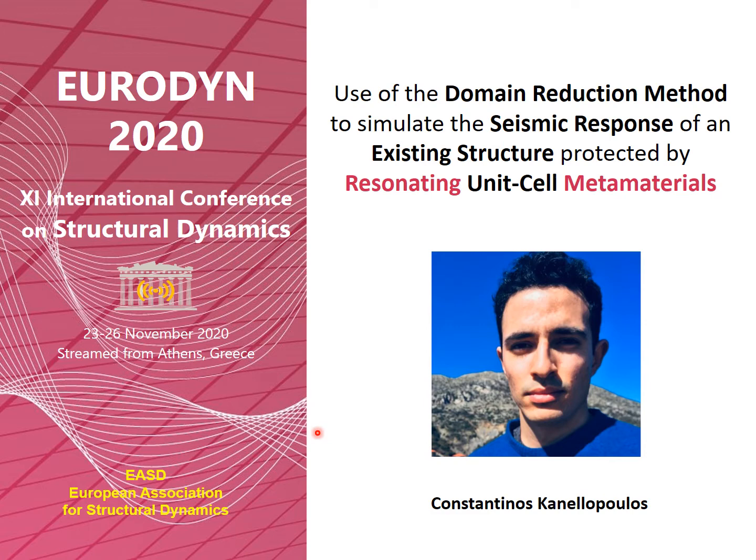My name is Constantinos and I'm a PhD student at ETH Zurich under the supervision of Professor Stojadinovic. In my PhD I'm working on seismic metamaterials implemented on a regional scale, which will eventually drive us to the concept of metacities. So in my presentation today I'm going to be talking about the use of the domain reduction method, which is a finite element method that we are using to realistically model the seismic wave field to simulate the seismic response of an existing structure protected by those resonating unit cell metamaterials.